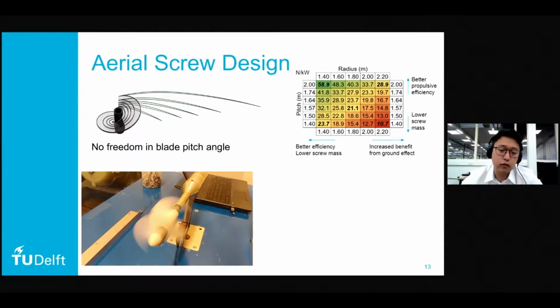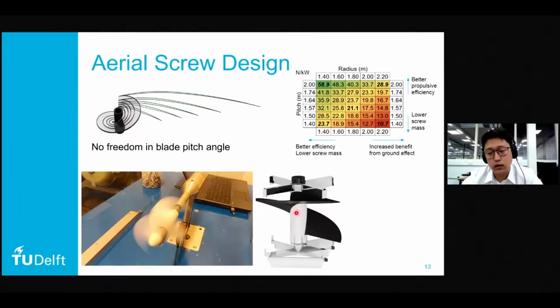And finally, we ended up with a screw shape like this. As you can see, the airfoil starts quite horizontal, parallel to the floor. And as you go towards the trailing edge, you end up with a steeper angle. We used camber like this because it was the only way we could control how much thrust we get in different flight conditions. We tune the camber along the radius in the same way you would adjust the chord and the blade pitch angle in a typical helicopter.